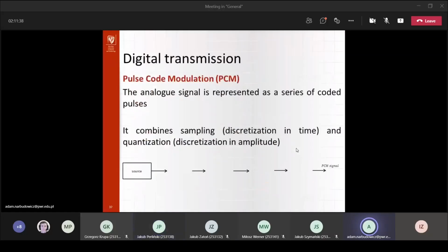If you take any signal, well, firstly, there will be noise which has an infinite spectrum. Also, if we're talking about acoustic or radio signals, it may have some higher frequency components. And after you do the sampling, those components will leak into your bandwidth and cause distortion.